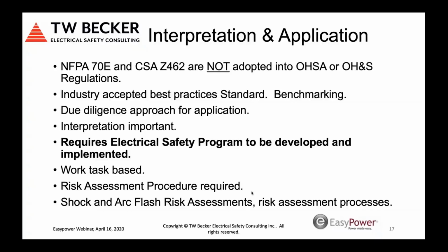Interpretation is important, and really the employer needs an electrical safety program. So it's really important that they have an electrical safety program. It is a mandatory requirement of 70E and Z462 as well. They are work case-based standards, so work task-based and risk assessment-based. So risk assessment procedures are required, and underneath that, you need shock and arc flash risk assessments. Again, those are also independently what I call true risk assessment processes.